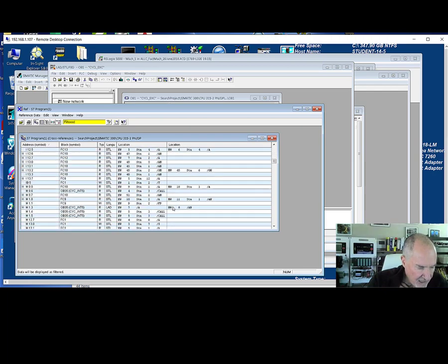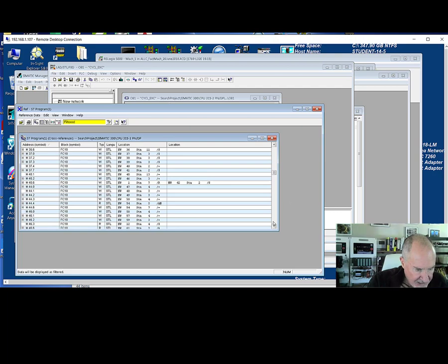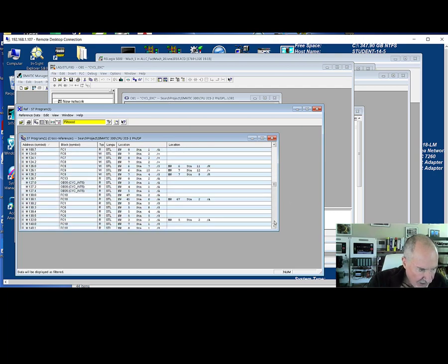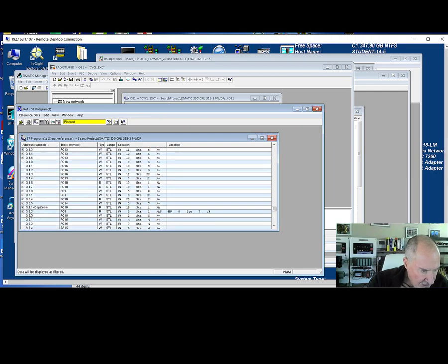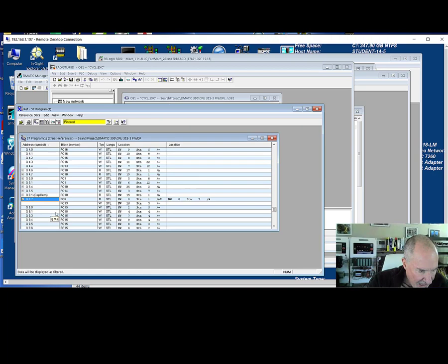And I'm going to do kind of like we would do in the class, right? Just pick an output and say what causes that output to operate. So let's say I'm in here in Q5.2, which is one of the outputs, is not operating correctly. So the place that I want to look for the output is I want to look for its coil. And for Siemens, the coil is signified by an equal sign.